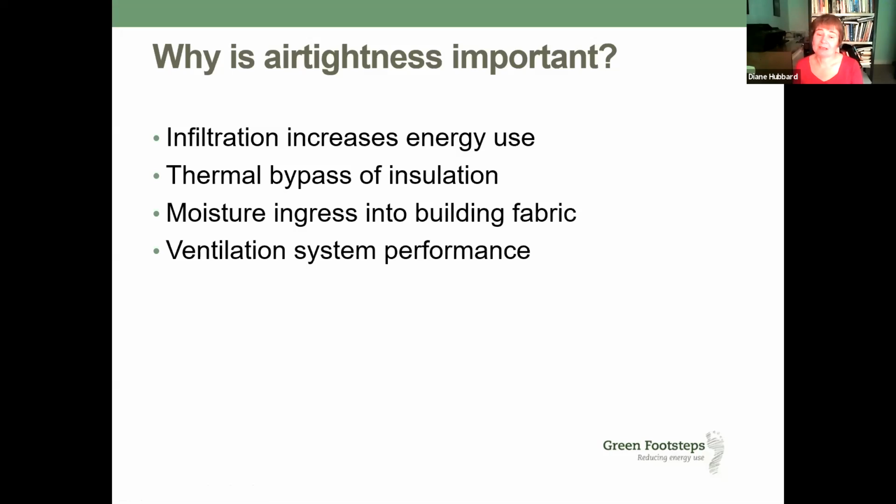So that means that insulation is in effect bypassed. The air moves around it, and so you don't get the performance of the insulation that you expect.